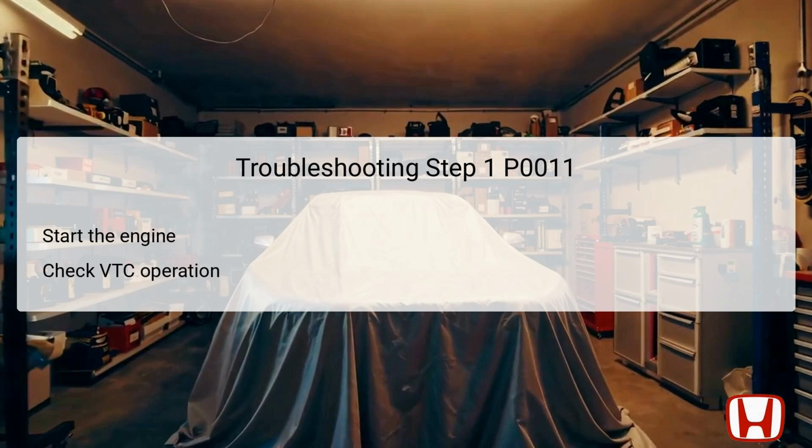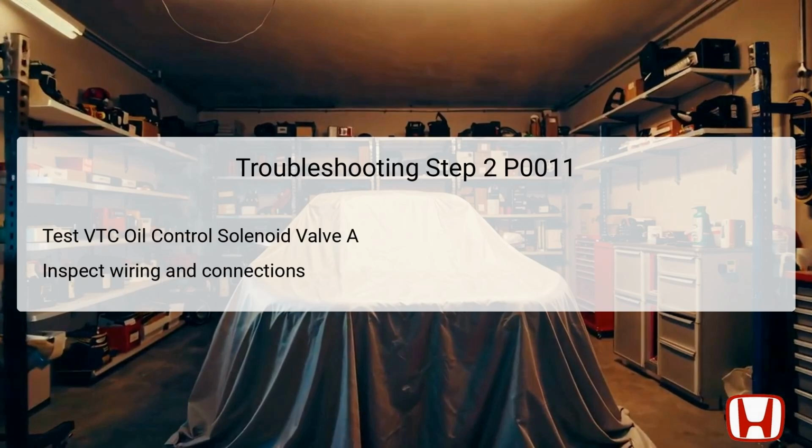This initial assessment is critical in identifying any immediate concerns that may point to a malfunctioning component. The second step in the troubleshooting process involves testing the VTC oil control solenoid valve A. This component plays a crucial role in controlling oil flow to the VTC actuator.